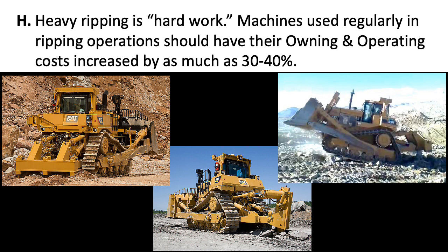Heavy ripping is hard work. Machines used regularly in ripping operations should have their owning and operating costs increased by as much as 30–40%.